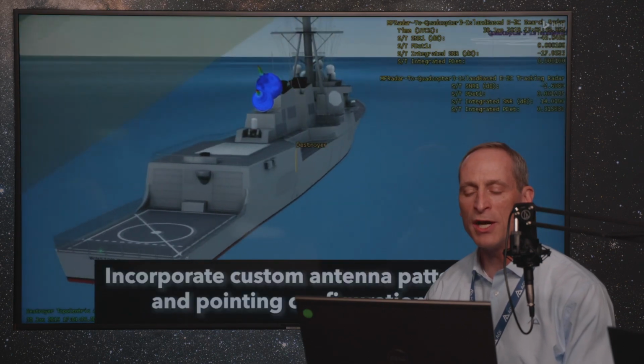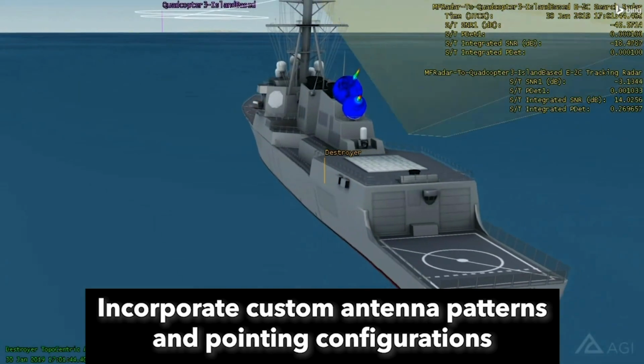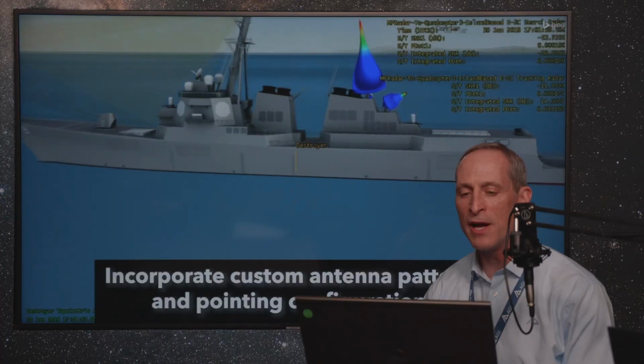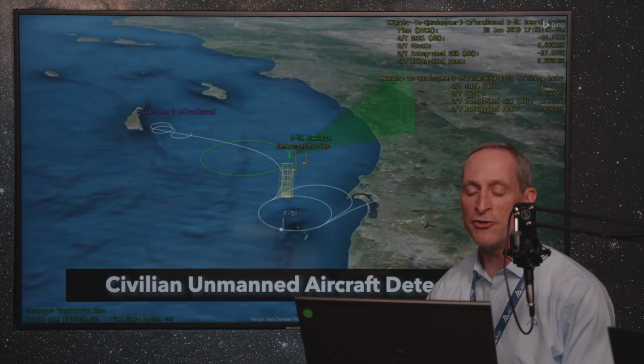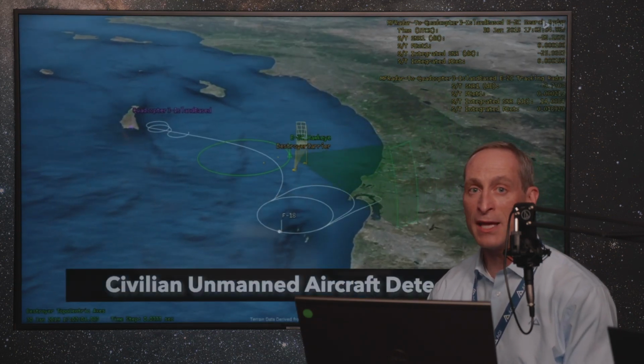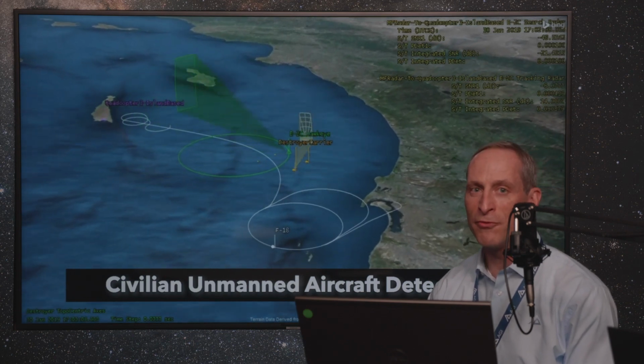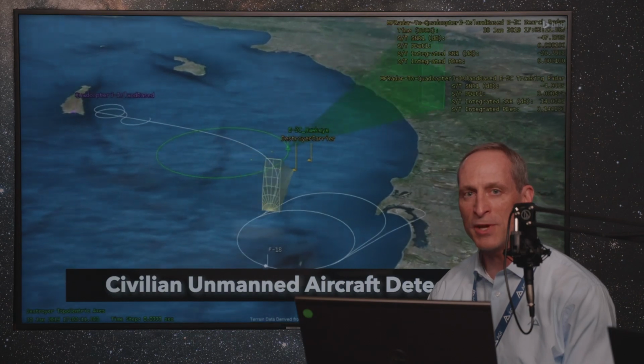In this case, what was done is we used a product from Ansys called HFSS to compute the high fidelity radar cross-section for the target under consideration, and also generate the as installed antenna patterns that would actually represent the physical performance of antennas on the ship that you just saw. So through this kind of integration, we're able to introduce that level of fidelity, a full physics level of fidelity, very early in the systems engineering process, whether that's for concept design or test planning.